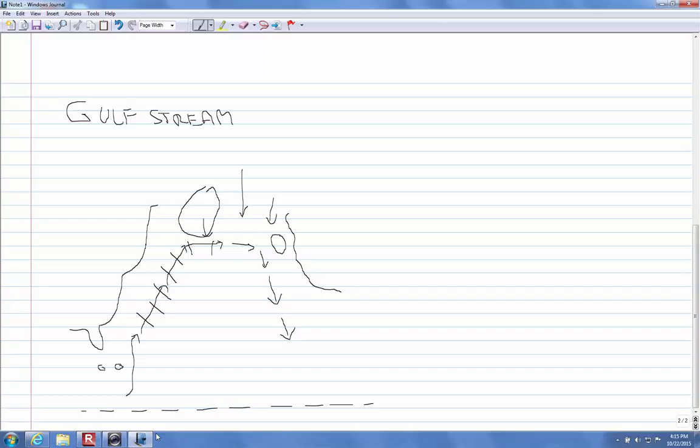So we got some issues. The book talks about the other issues in there, and you guys talk about wave energy in chapter 8. But for now, just talking about anything that you put on the ocean. It's highly corrosive, so we're dealing with corrosion. Anytime you put metal in the ocean, it's called galvanic action or electrolysis. You have something moving through salt water. It causes an electrical charge, and that electrical charge will actually erode the metal. It pits it and erodes it and eventually destroys it.